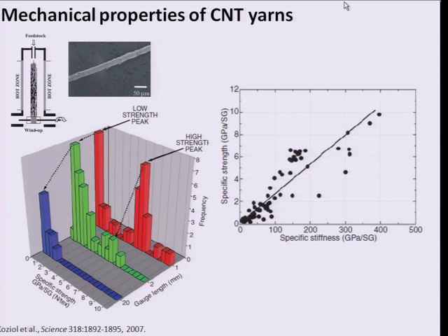And in this case, by making nanotubes that are much higher quality than were in those forests, they've been able to achieve specific strengths of about 10 newtons per tex, or about 10 GPa in the best cases, which is about a factor of 10 beneath the strength of individual nanotubes. But in fact, what they see is a bimodal distribution of strengths as a function of the gauge length of the specimen. The gauge length means how large the gap is between their loading axes. So taking a piece of yarn and grabbing it across a 1 millimeter gap versus a 20 millimeter gap.